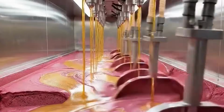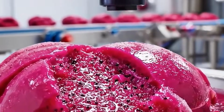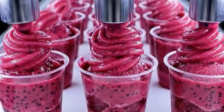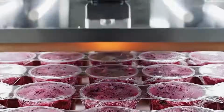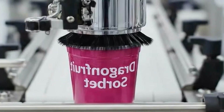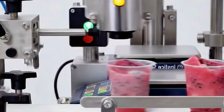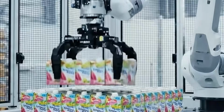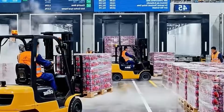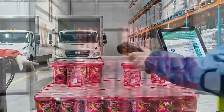This is a spiral or straight belt blast freezer, where ambient air temperature is held at -35 to -45 degrees Celsius. Air is circulated at high speed to ensure fast freezing rates. Dwell time inside the tunnel ranges from 30 to 90 minutes, and the goal is to reduce the core temperature of each unit to below -18 degrees Celsius. Faster hardening reduces ice crystal size and improves long-term texture stability. Core temperatures are verified by infrared sensors or penetrating thermocouples on randomly sampled units.